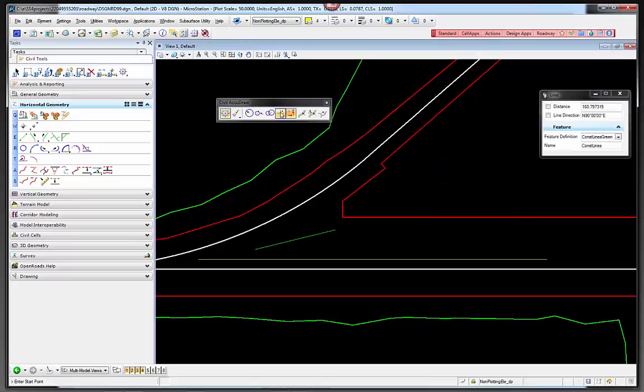So what I was pointing out, though, is that you have the same sort of tools with AccuDraw, but if you're going to stay within Civil AccuDraw, you might want to have those same capabilities. So that's why the XY and the DXY is in there. And then you have the Station Offset, which is a way to locate something off of a line. So let's say I needed to start a line, and I need to switch this to the Station Offset.